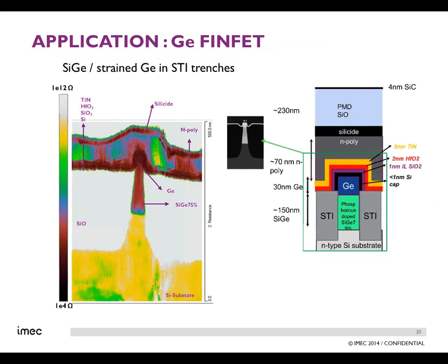We use III-Vs. We also use germanium, which is also a high mobility material. Same concepts. These germanium layers are grown on top of silicon, and silicon germanium is also used in this case. So you have silicon, then silicon germanium, and then germanium on top. This is because the lattice size of these different materials is different, so we typically use materials which have lattice dimensions in between the one of the bottom material, silicon in this case, and the desired material that you want to grow, in this case germanium.